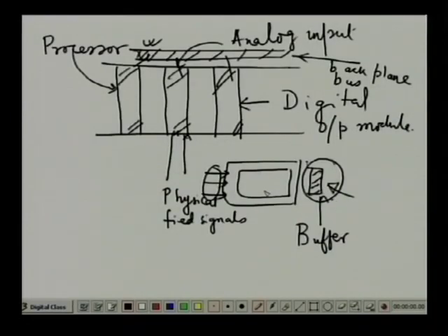So actually two activities keep on taking place. The first one is that the physical signals keep getting transformed to these buffers, and these buffers could be physically situated either on the card, or it could even be situated in the processor memory. Those who have studied microprocessors will understand this: it may so happen that these cards every few units of time convert these values, and then using some interrupt mechanism they will transfer these values to some part of the processor memory.